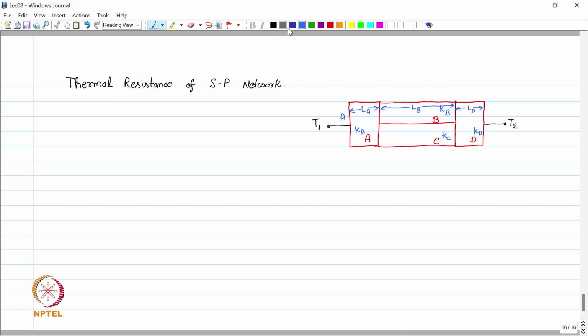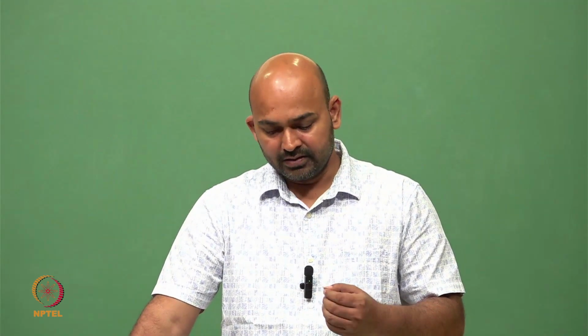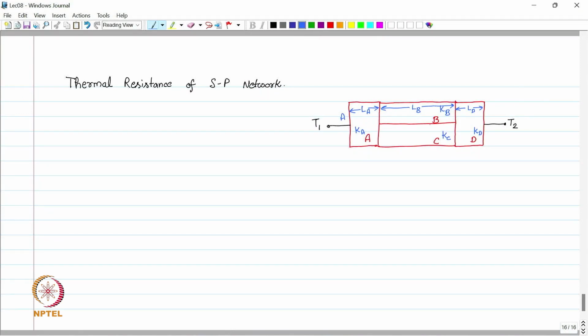So now we need to make an assumption here. Similarly, in the first slide, we had the assumption that at the point of contact, the temperature is the same across the surface. So a similar assumption we need to make here, that there is no temperature difference perpendicular to the x-axis. For example, the heat is flowing in the x direction. The heat flow is this side, and there is no heat flow perpendicular to this. Means the surfaces which are normal to x direction are isothermal.